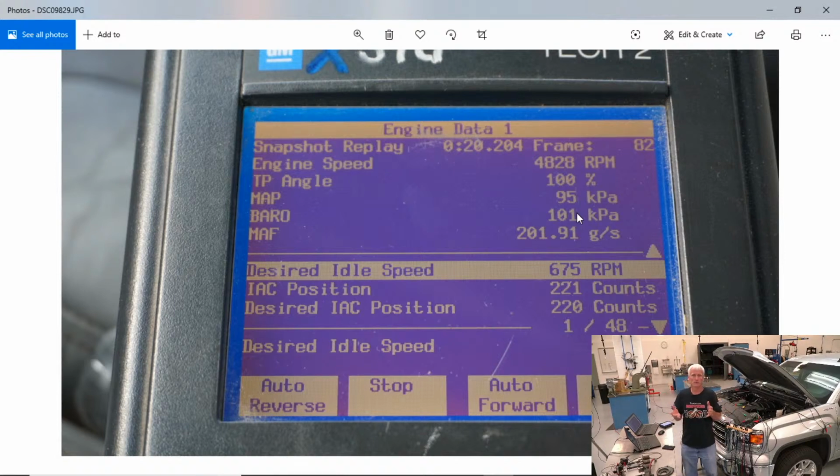The long-term fuel trim is how far off the baseline, how far off the program the computer had in there, calibrated based off the engine speed and the amount of air coming in. The long-term fuel trim is going to adjust for things that are throwing that off. So if my mass airflow sensor was misreporting, and in reality this engine is 85% efficient, but it's only reporting 75% of the air coming in, there's air coming in that it didn't realize, didn't report on. So I'd look at my fuel trim numbers to see if the fuel trim's saying I needed to add fuel.